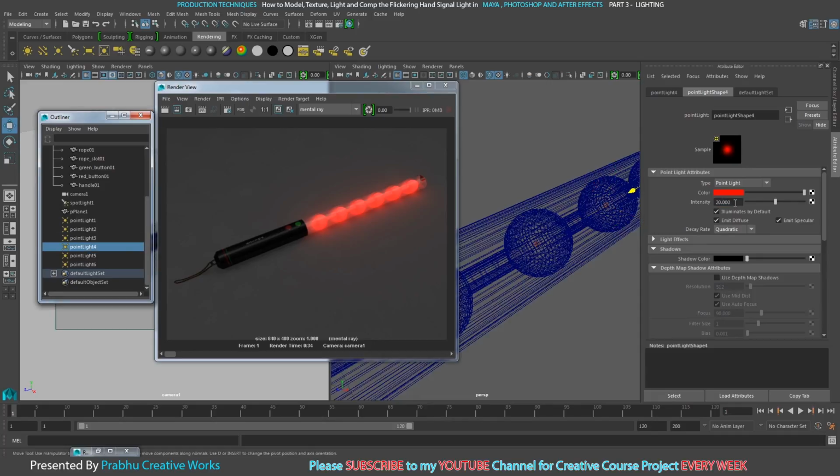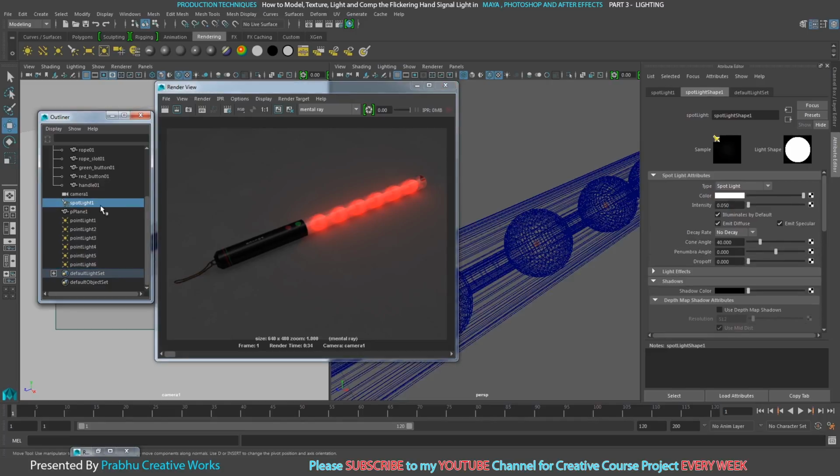So you cannot fix any constant values for our lighting purpose, it depends upon our field. So I will compare this one and click render again. Okay, it's really cool, but I want to reduce my scene intensity, so I select my point light and reduce it much more, so I will give 0.020. I will compare this one. So see here, I have reduced my scene intensity, so it will look bright.